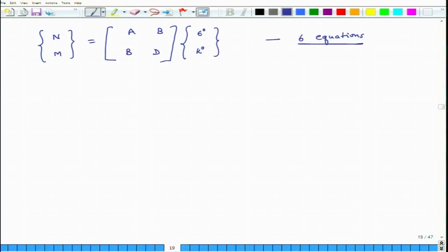And so we will consider each matrix term individually. So, first we will look at Aij, which is the ij element of A matrix. This was defined as Qij bar for the kth layer times hk, which is the coordinate of the bottom portion of that layer, minus hk minus 1, and we do this summation from first layer to all the n layers.